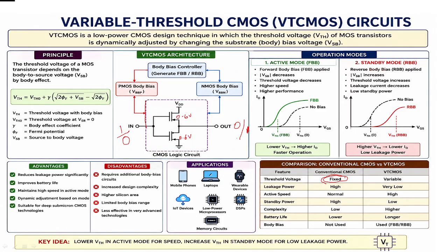This is the traditional method. But our aim in VLSI is always to reduce the power consumption. So here we are using some extra biasing, an extra power supply to bias the body, and we can reduce the threshold from 0.6 volts to 0.2 volts. Just assume that. And here also, by using extra biasing, we are reducing 0.6 to 0.2.